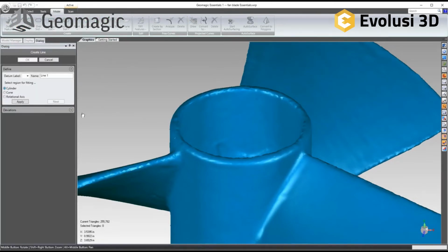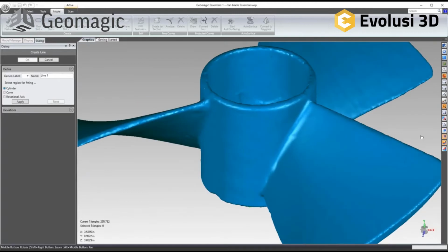cylinder axis. So you can use the same tools that we use for selection, the lasso tool, but make sure that you turn off select through and toggle it back over to select visible. So you can window in areas like this to select that outer cylinder to create a cylinder axis. But what I like to do is use this option right here, this crease angle tool.